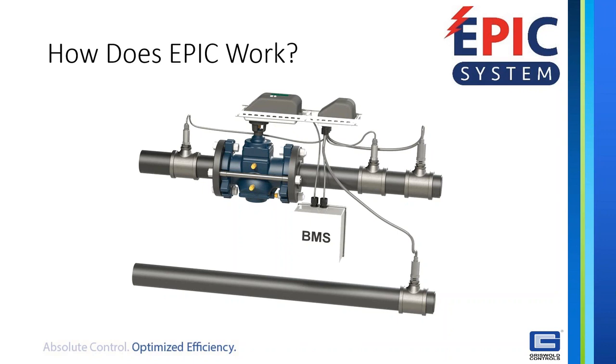So the thermostat is actually not controlling the valve. The thermostat is controlling the coil, and then the coil is impacting the delta T, and then the delta T sensors read that, and as they read that, they adjust to correct the delta T. So the EPIC system is really the next phase in evolution for control systems, and we do have a quick little 10-minute video about that.